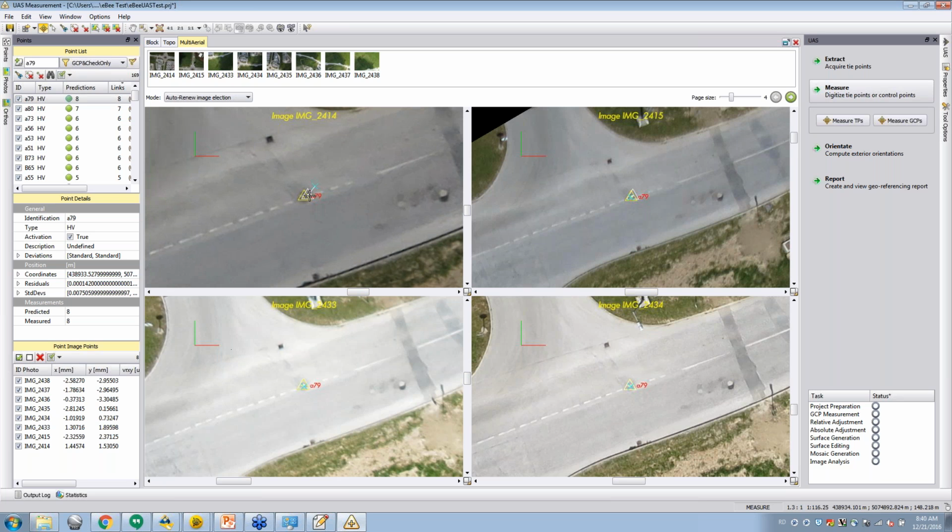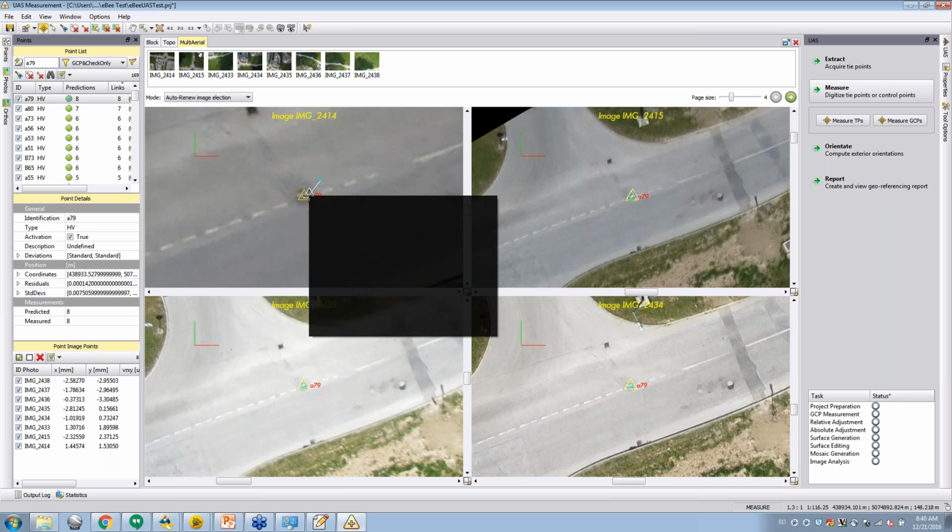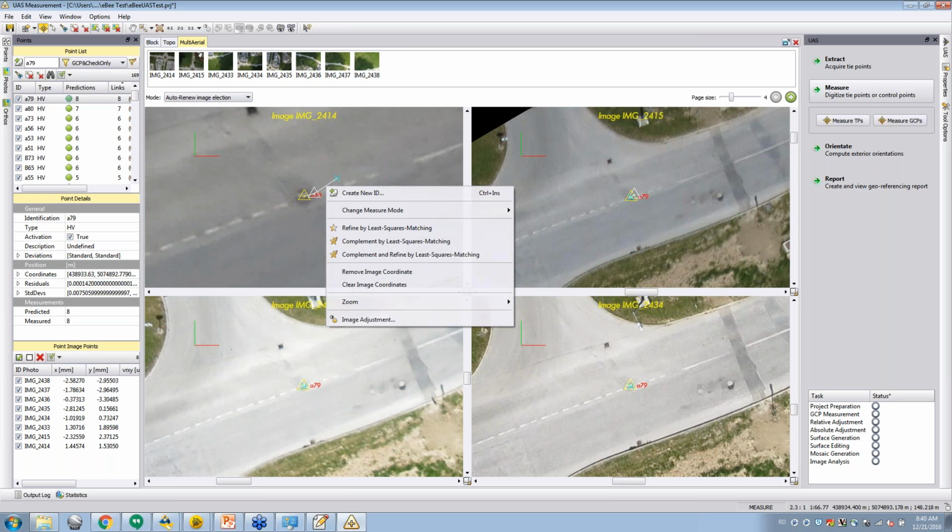So if I click here, we can see that there are 3 measurement types. I'm in manual. There's a manual, semi-automatic, and fully automatic. Semi-automatic, pretty much when you click on every GCP point, it uses the least squares to compare each image so that it actually goes subpixel and makes the selection of that GCP more accurate. Manual would just be you click and that's the measurement.